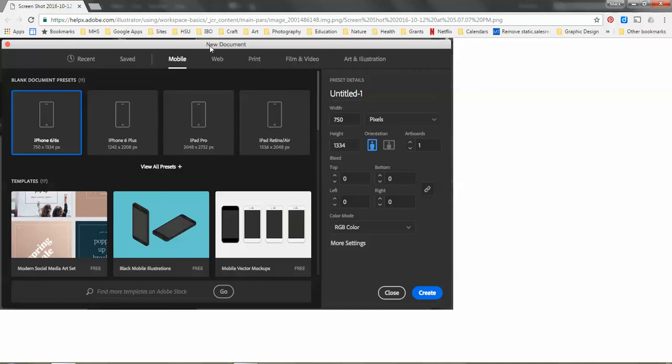So what you need to do in the New Document dialog box is go over, click right here where it says Web, and you'll see some little size preview buttons in rows here on this side. You can go down and find the one that says Common 1366 by 768. Then go over here and title your project Ribbon Tree with your name and click Create.